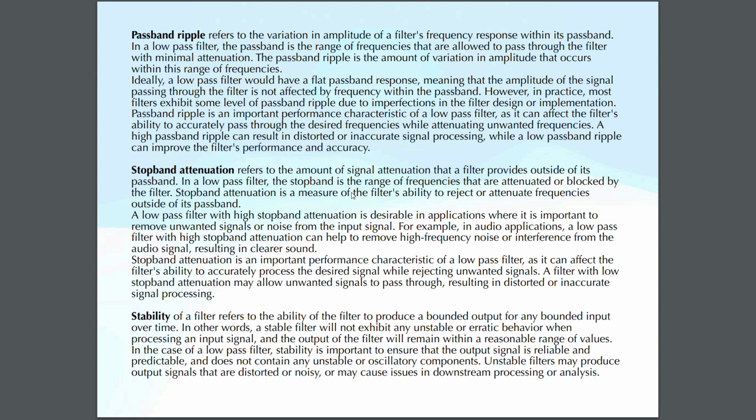This refers to the ability of the filter to produce a bounded output for any bounded input you give over intervals of time. In other words, a stable filter will not exhibit any unstable or erratic behavior when processing an input signal, and the output of the filter will remain within a reasonable range of values.